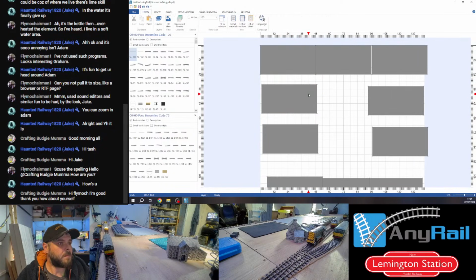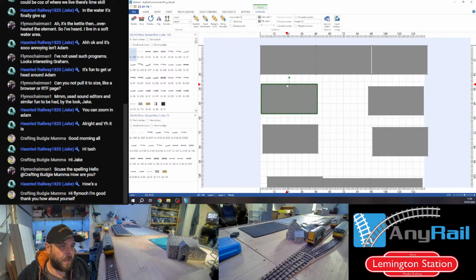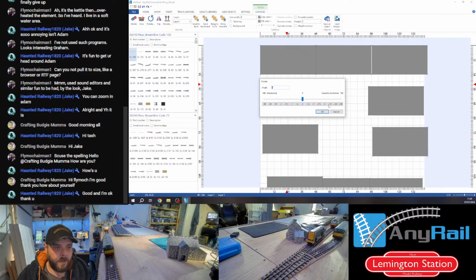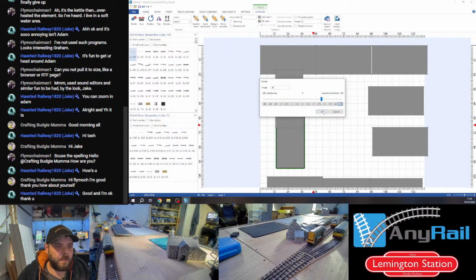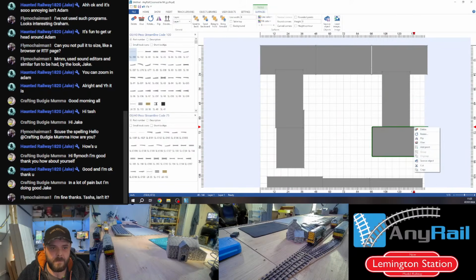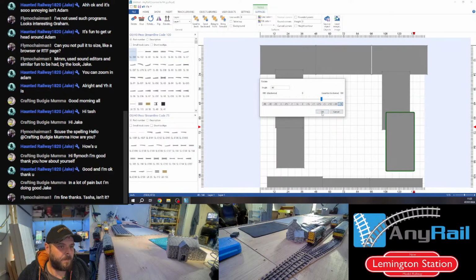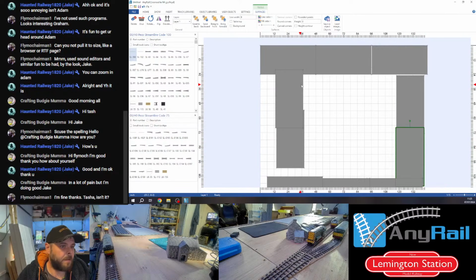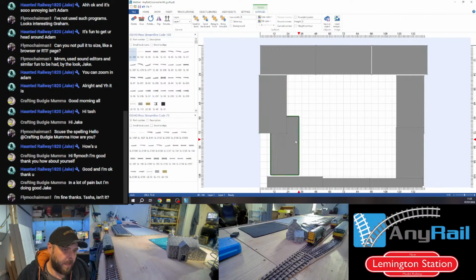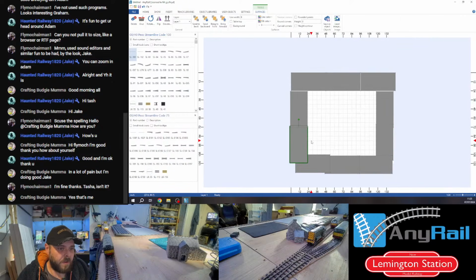Or you can select it, you can right click, and then you can rotate it, and then there are buttons across the bottom here that give you exact degrees of movement so that you can move it an exact amount. So I'm going to move that 90 degrees, and I'm going to do the same to the other 4. Just move these roughly into place. They don't need to be exact because you can move them with the move surface tool afterwards.